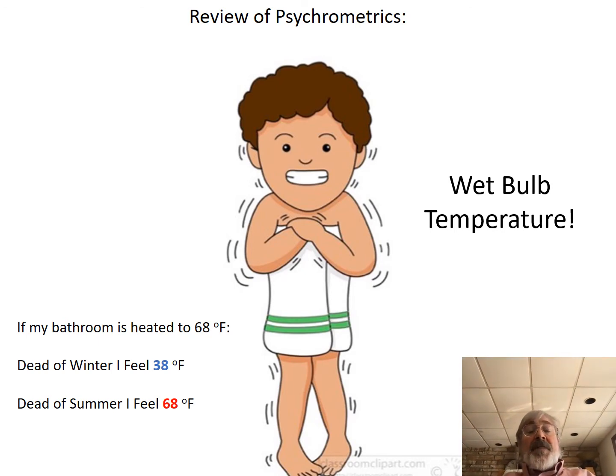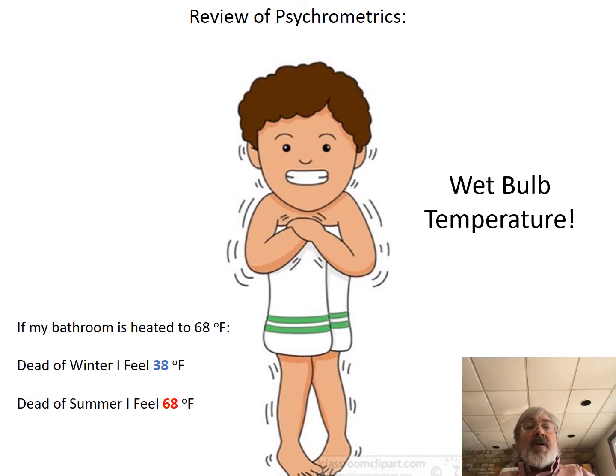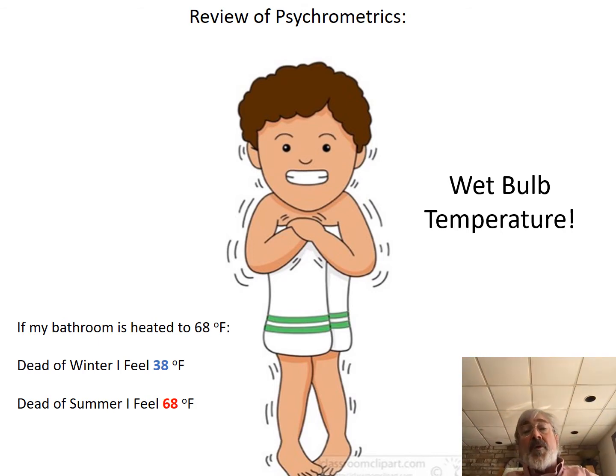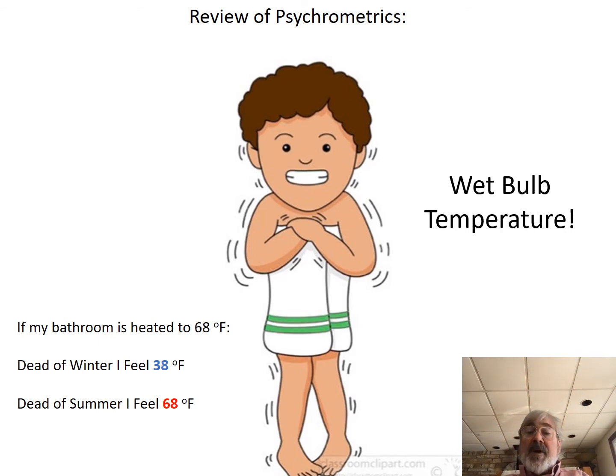So if I think about me being a grain of malt sitting in a pile of other grains of malt, and air gets hit to me, the same exact thing happens. The grain doesn't experience the air temperature. The grain experiences the wet bulb temperature, or something in between the dry bulb temperature and the wet bulb temperature, depending on how much water is evaporating. All right, we'll get into this more later.